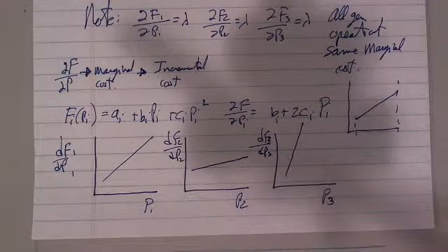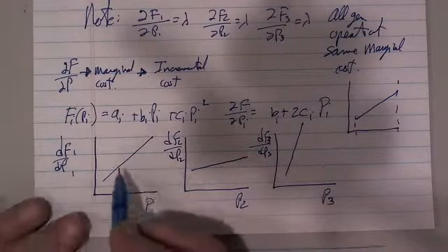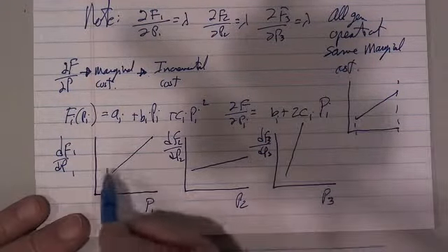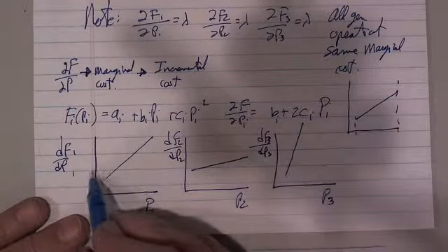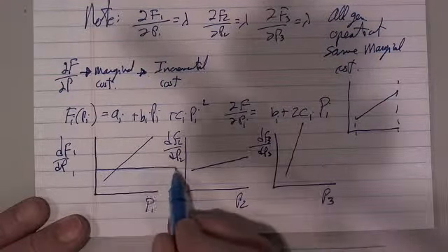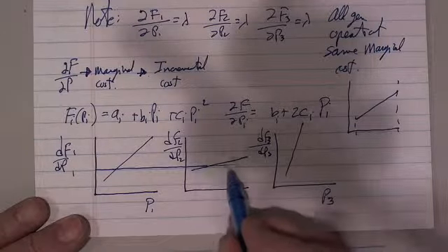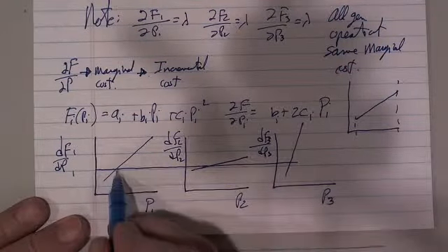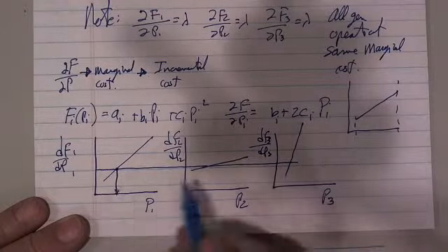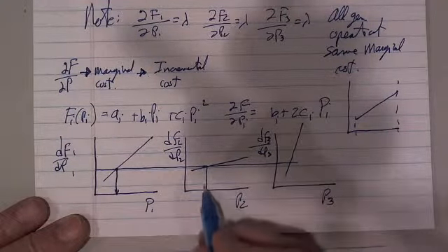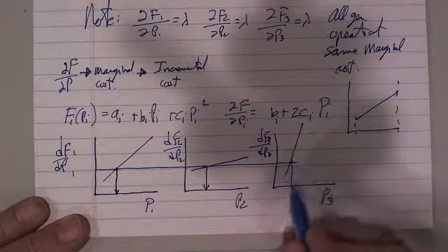That's okay. Now, if I wanted to get a dispatch where the same incremental cost applied to each one, I could draw a horizontal line, and then I could say, well, it intersects there, so that's P1, and that's P2, and that's P3.